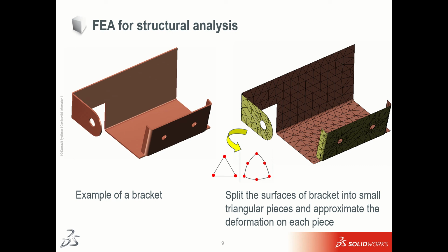After that, there are 2D elements, which are plane linear triangular. Here also you can see two elements. Basically, this is a draft quality element which contains 3 nodes, and this is a high quality one. In between 2 nodes, you get 1 extra node, which makes it 6 nodes instead of 3. And here, the degrees of freedom for your element is 6, means it contains all degrees of freedom.